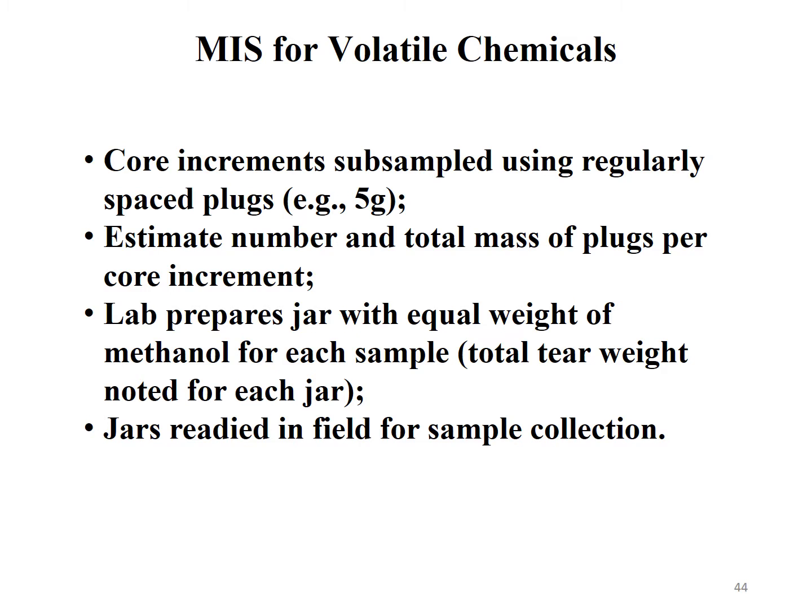So I've mentioned earlier most of these points about when you're looking at volatiles that we're generally using methanol, so you're putting roughly equal weights of methanol per gram of soil you're putting into that jar, and it's very essential that you coordinate closely, of course, with the lab, because the lab has to provide an adequate amount of methanol, usually fairly large volumes, to accommodate the multi-increment samples from numerous cores that are going to go into that multi-increment sample in methanol.